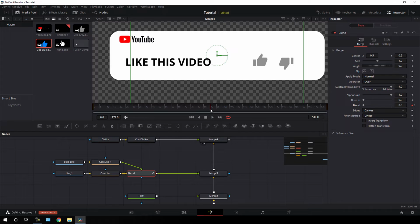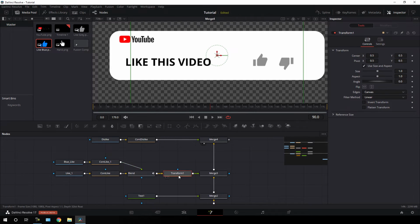All right, and now we have to create a click animation for this like button. So what we have to do, just select this blend, click on this transform button, and this transform is going to be click animation. So hit F2 on the keyboard, call it click, and now you can animate the size of this.